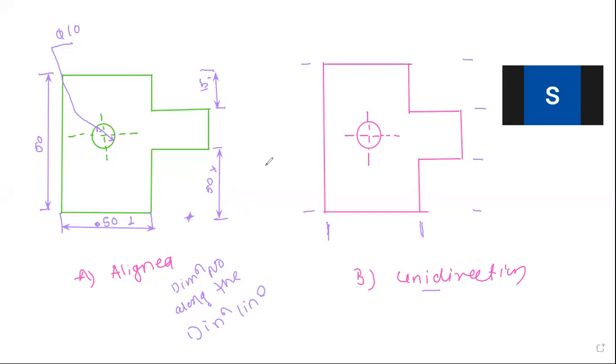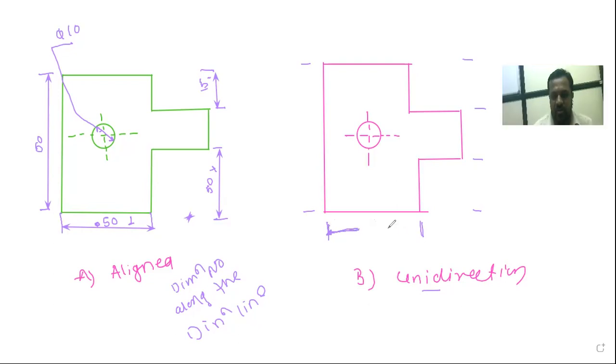Please tell me what is the condition for this dimension line in this system? Between the line, yes, that line should be broken down. Like this. Your dimension line should be like this, your dimension line should be broken down, and in between this line we have to write down the dimension numbers.